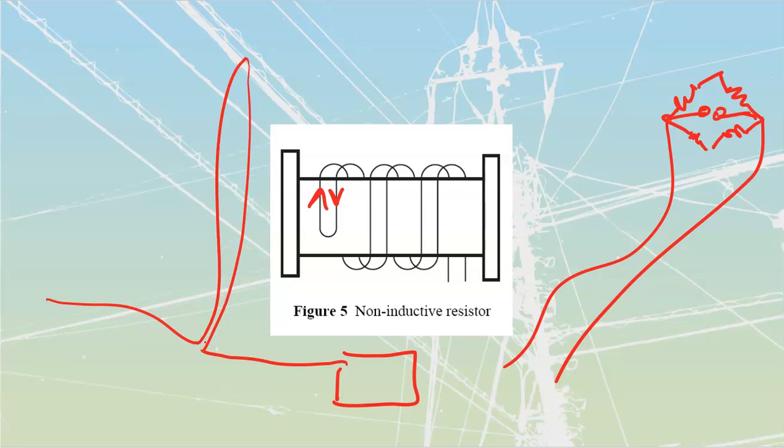Not tight, you don't want to crimp it with your pliers or anything stupid like that. But once you get this thing folded in half, then you take this folded set of wires and start coiling that folded set of wires up. That way you've got cancellation of all flux and you're not going to be creating any sort of inaccurate measurements out of them.